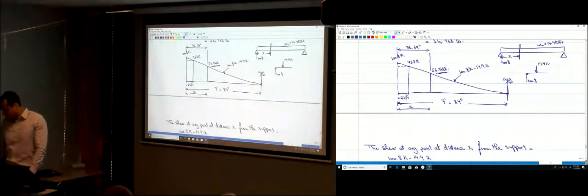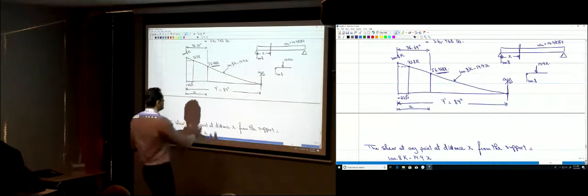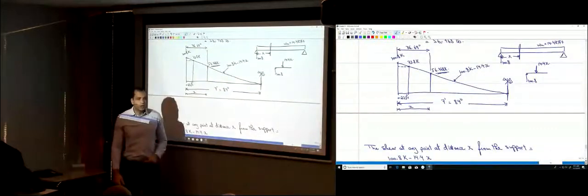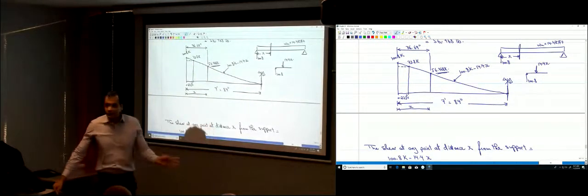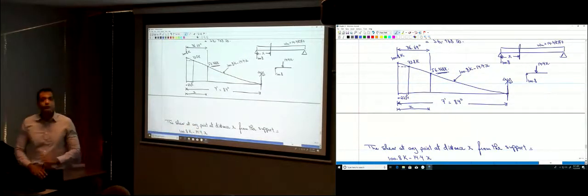Now, at what point should I provide those 9 inches of spacing everywhere here? No. We know that at some point you don't need stirrups at all. What is that point where you don't need stirrups at all? When V_c over 2 is greater than V_u. Exactly. So let's find that point where you don't need stirrups.